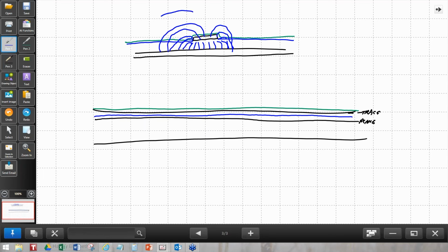To the extent that you have signal lines coming off of this trace that go up and out before coming down to the reference plane, going through the layer of solder mask, the dielectric constant of that solder mask can be substantial. And so whether you have it and whether or not it's thick or not will affect the characteristic impedance of the traces.